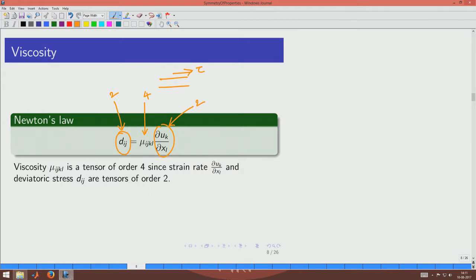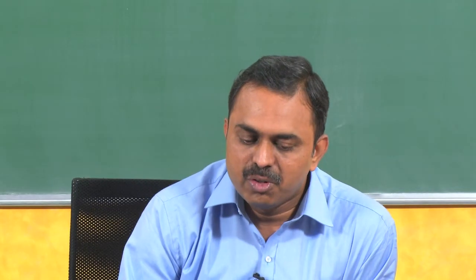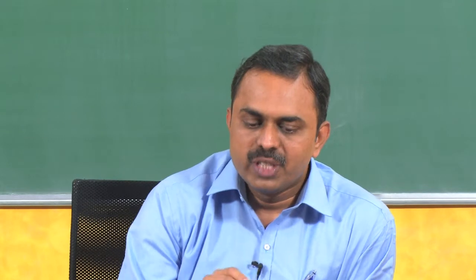The reason is that we normally know viscosity to have just one value for a given liquid, and a tensor of order 4 would require 81 different numbers to represent it completely. So, when did 81 become just 1? This is something that we will discover a little later in this course, but at this point we only want to state that using the quotient theorem and also using the expression for the constitutive relationship, we can deduce that the maximum possible order for viscosity is 4.